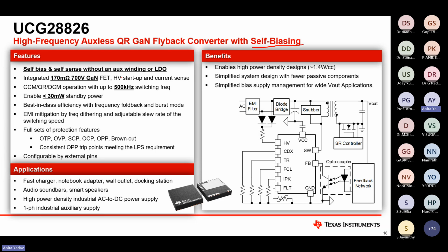Standby power is when we are connecting our circuit to the supply, but the load is not connected, and there is still internal circuitry drawing some current, and thus some power loss is happening. So from that perspective, this part lets you achieve very low standby power, and this is a very good point. We have less than 30 milliwatts.